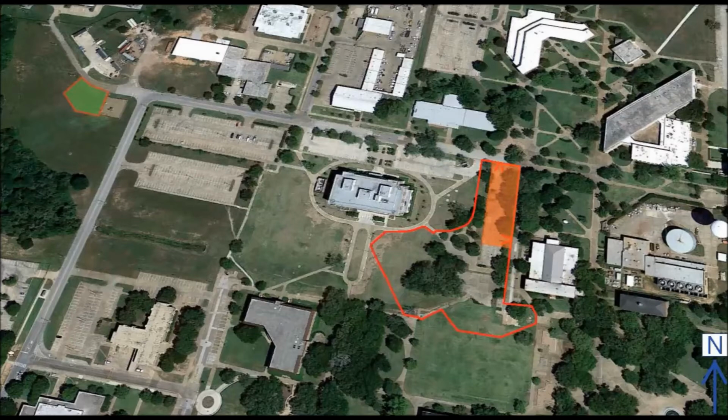The primary laydown area for the project, shown in orange, will be located at the northeast corner of the site. The building, shown in blue, will be centrally located on the site. The crane, shown in yellow, will be positioned between the building and the laydown area. This will increase efficiency since it will decrease the number of times that materials will need to be moved around the site. The pedestrian pathway is shown in purple. Existing sidewalks will remain unobstructed for navigation around the site.